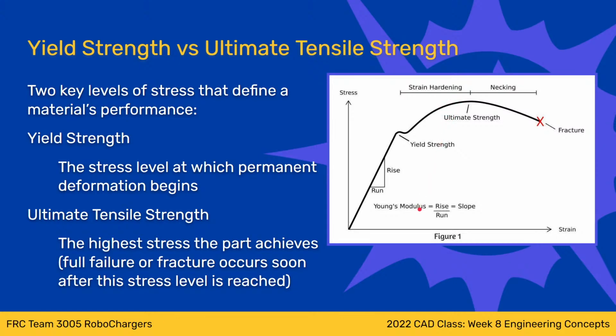I have hardened the material even more. And if I keep bending the piece of material back and forth, eventually the material gets so hard that you can't deform it very much at all, and it just cracks and it fails. And so essentially that's what work hardening is. That's what strain hardening is. Work hardening is kind of a more practical term for strain hardening, but they're basically the same thing.